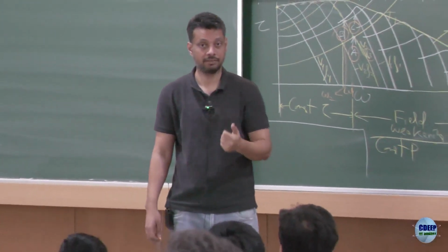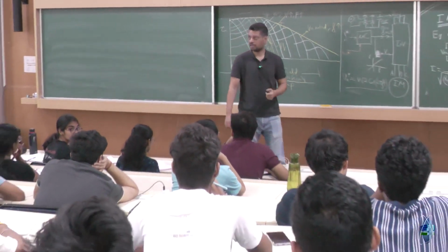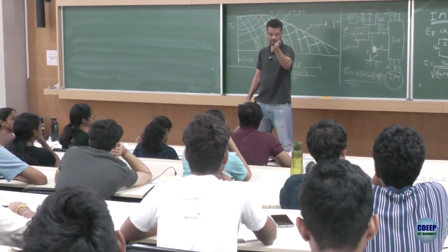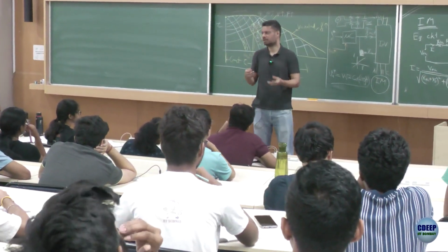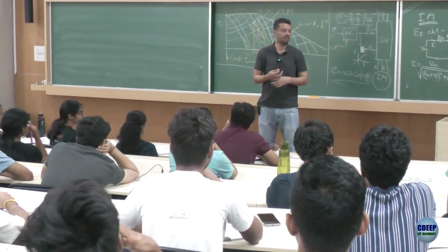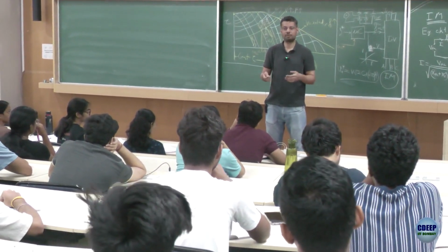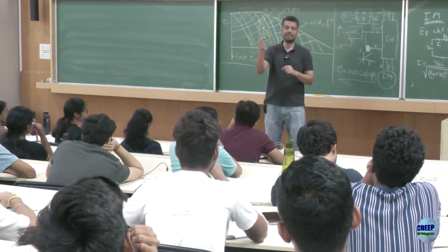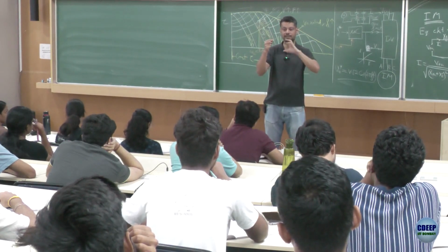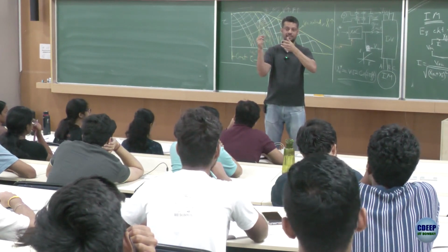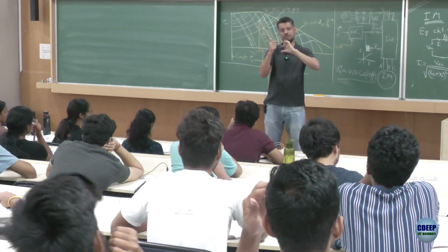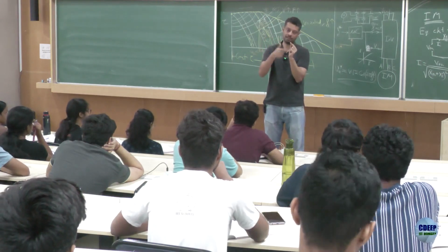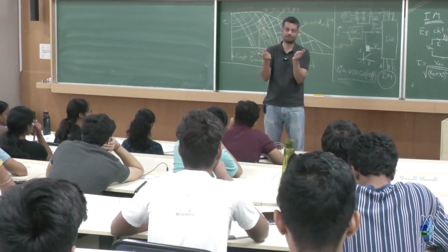How do you measure the speed? You can't use a tachometer, okay. So that's a question. Let me answer yours first. His question is, how do you actually measure the speed? So what is a tachometer? A tachometer could be some form of an LED light or an IR light, and some disc is rotating, and it's just counting the number of pulses that the light emits and the receiver receives over 1 second. That's how you would get rotations per second.